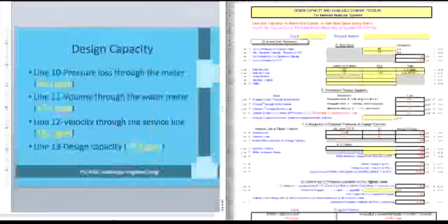But fortunately, the worksheet has already calculated a lot of that information for you. As I mentioned before, we didn't have any isolation valves or other pressure losses. So down here, the total pressure losses from the source to the point of connection are calculated, and it just added all of these different potential pressure losses together for a total of 5.75 psi. So now let's keep going. Got a little ahead of myself on the worksheet here. Let's keep going.